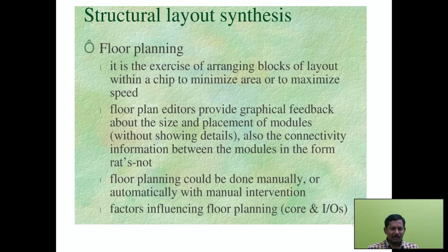Next type is structural layout synthesis. Majorly it consists of floor planning. Floor planning is the exercise of arranging the blocks of layout within the chip to minimize the area or maximize the speed. For example, in civil construction, they will give a land area.